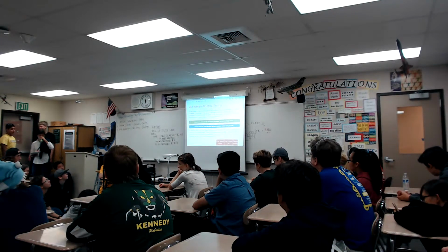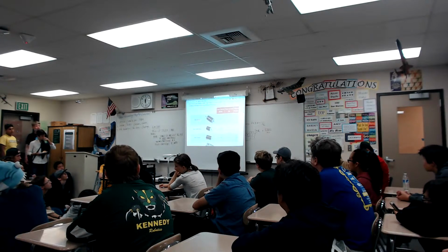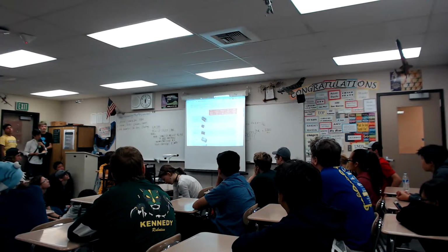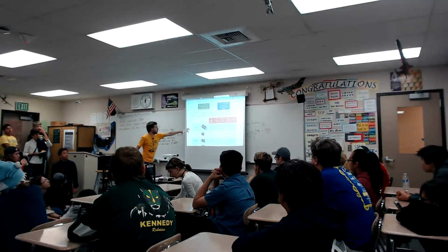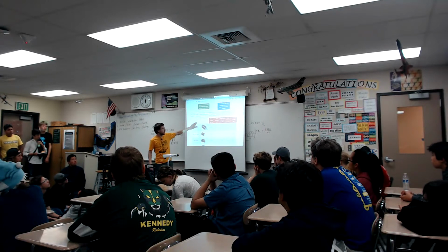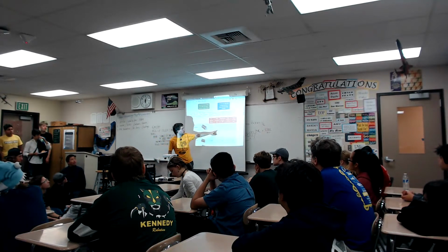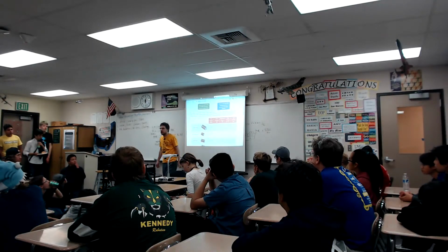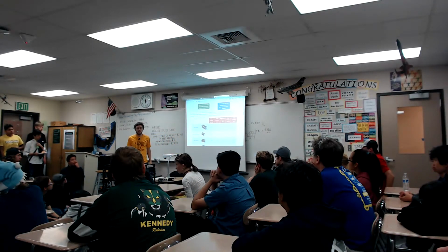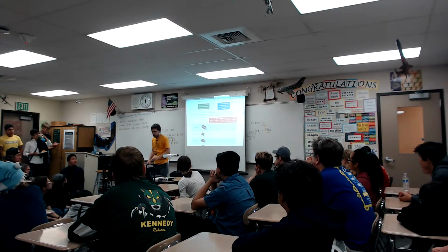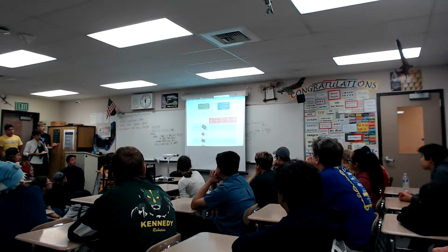Okay, so motors.vexpro.com. Zoom a little bit. There we go. So here's where I was pulling those numbers from. We can see here's our free speed for a sim, free speed for a mini sim, bag motor, all the various motors as you scroll down. We're pretty much ignoring the free current in this because it's compared to 131 amps, 2 amps isn't very much. And then our stall torque.